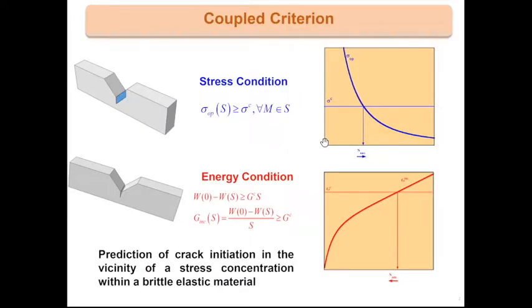So let us imagine you have a solid here and a stress concentrator, for example a sharp notch, and you submit the sample to a tensile loading, and you would like to predict the crack initiation here. Of course, it's not a standard problem because you do not have a crack, but a notch, a stress concentrator, and you cannot use a standard approach of fracture mechanics.